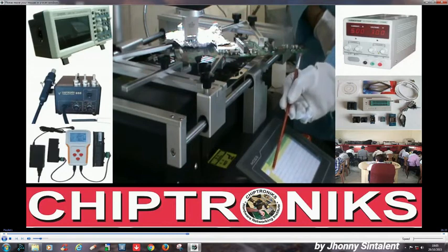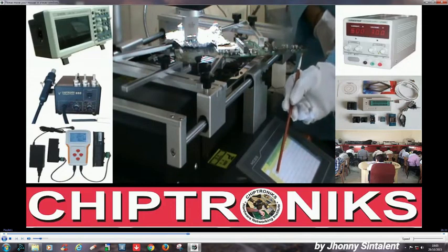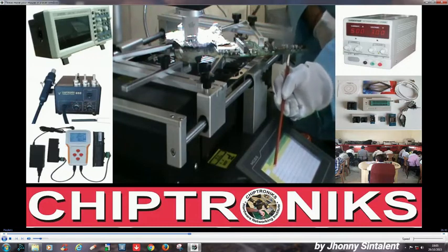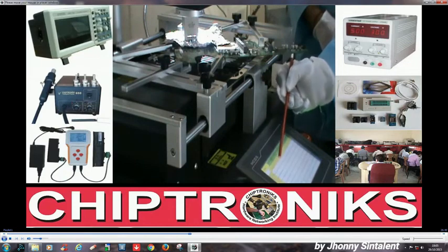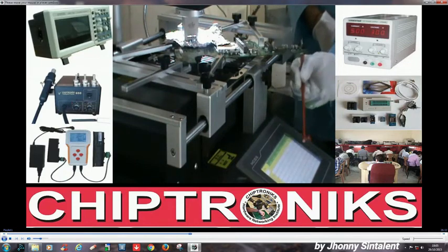And here you can see this is the upper temperature, lower temperature, and infrared temperature, and this is the rate at which the temperature will increase. Basically this BGA machine has a PID controller. The PID controller will reach this value of 150 from 185 via this rate. So that rate is the increasing temperature value, how much the temperature will increase.